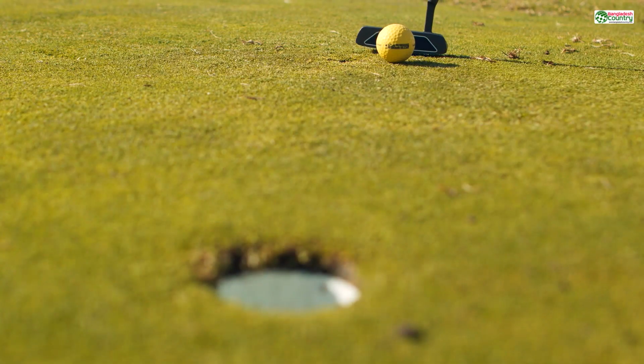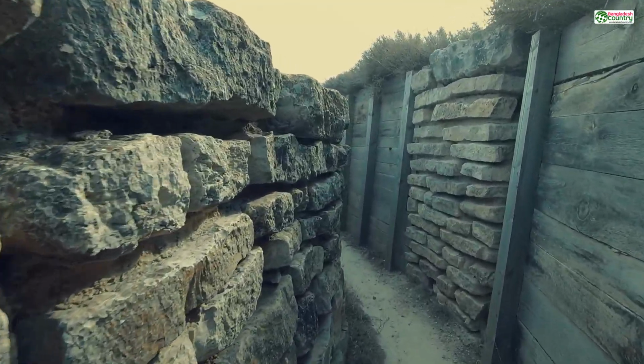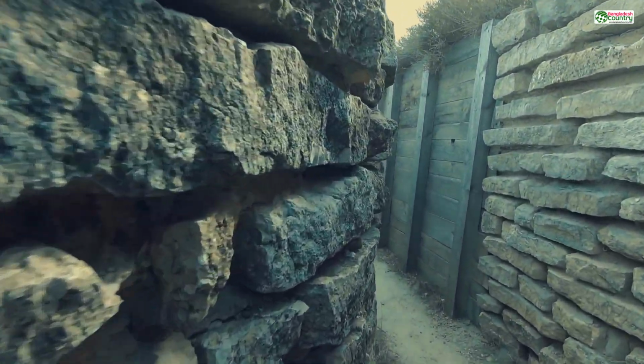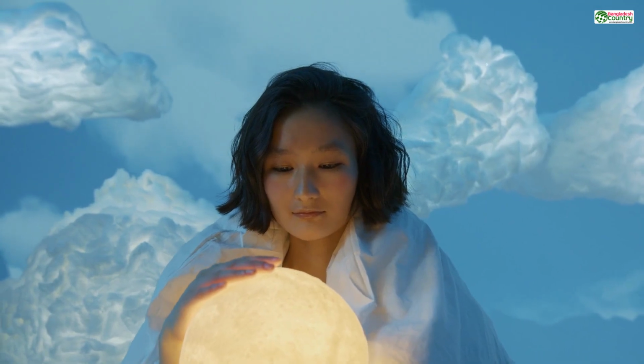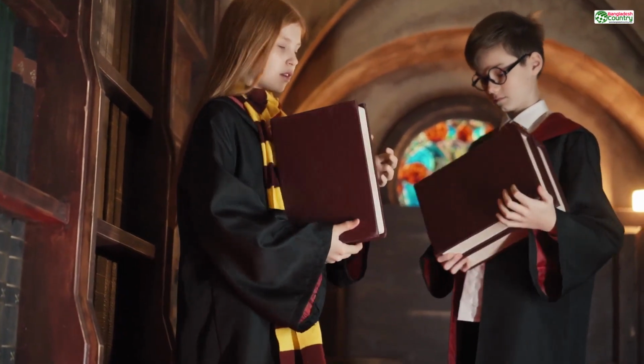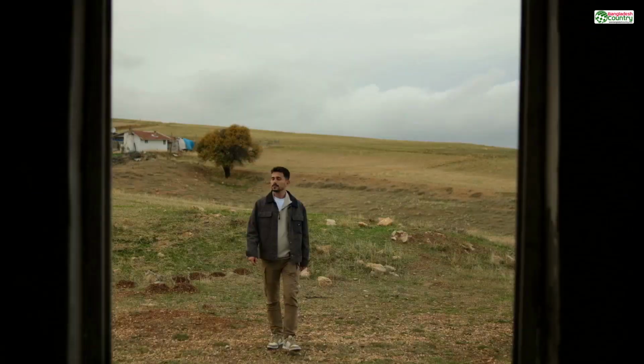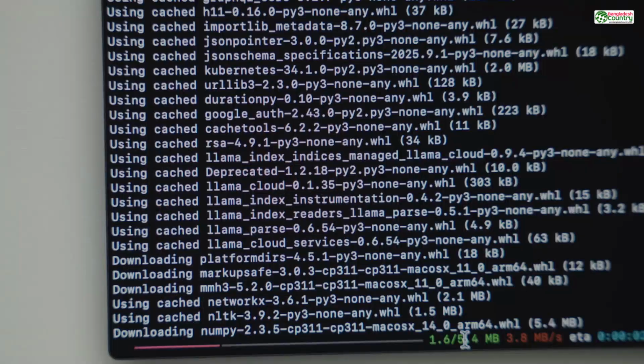The second culprit is more insidious: internal faces. These are walls, surfaces, and bits of geometry hidden inside your supposedly solid model. Imagine you're building a 3D model of a simple house. Now imagine you accidentally build a wall that runs right through the middle of the living room, completely sealed off with no doors. You can't see it from the outside, but the slicer software can, and it gets confused.